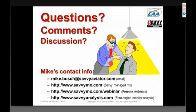Other kinds of instruments will use thermistor gauges, which have a probe that varies in resistance by temperature rather than generating a voltage the way the thermocouple probe does. The problem with thermistor probes is that because they vary resistance, they're very sensitive to anything in the system that would introduce spurious resistance, like connectors. Those tend to be a little less trustworthy.